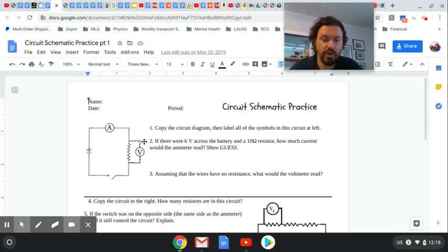It's also showing that you're using the voltmeter and using the two prongs, one here and one there. You're using both to span this resistor, one on one side, one on the other, just to see what the voltage is across it. Because once you know the voltage across it, you could figure out the resistance, how much it's resisting, especially if you already know the current from right here. This gives you two of the three pieces of information, and from there you can figure out the third.